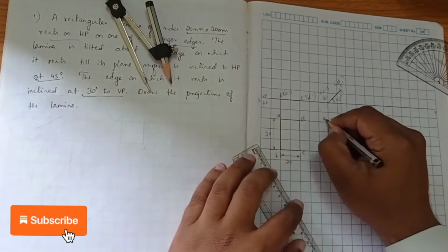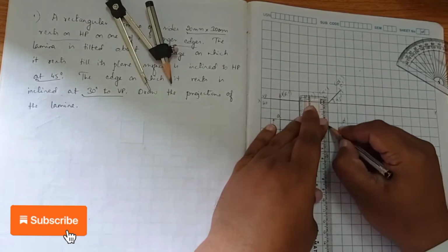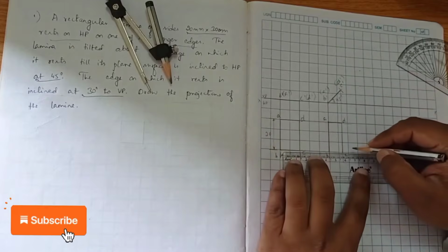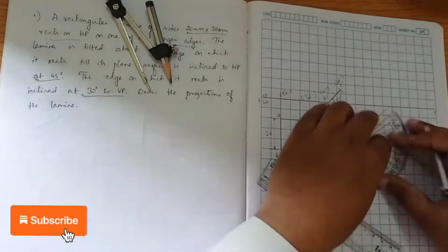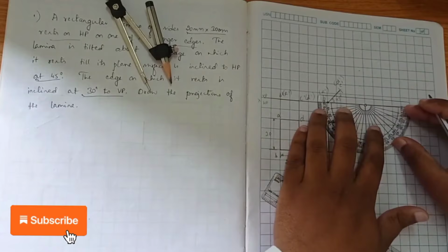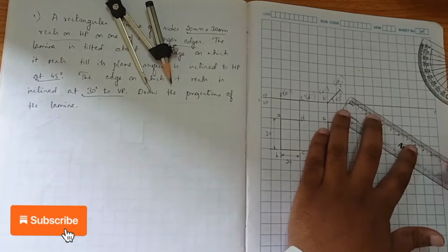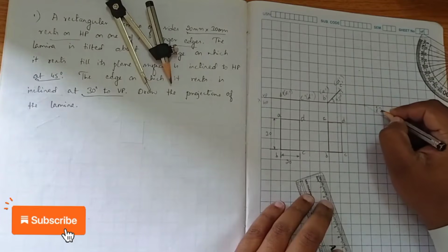So here A, B, C and D. This is the second position top view. Now inclination to VP is 30 degrees. Take a reference point here, and mark 30 degrees.